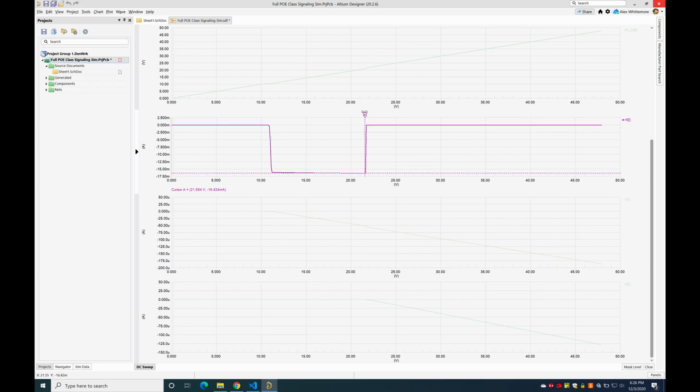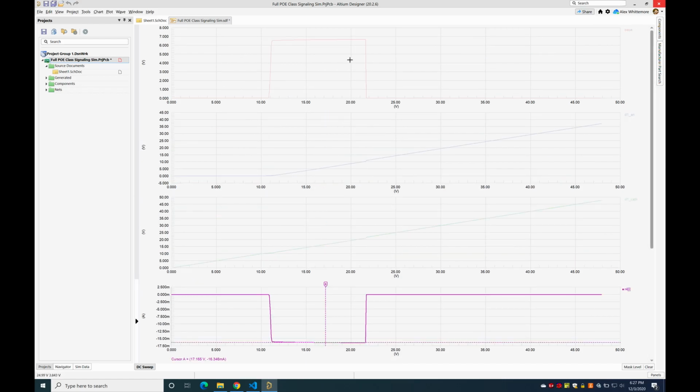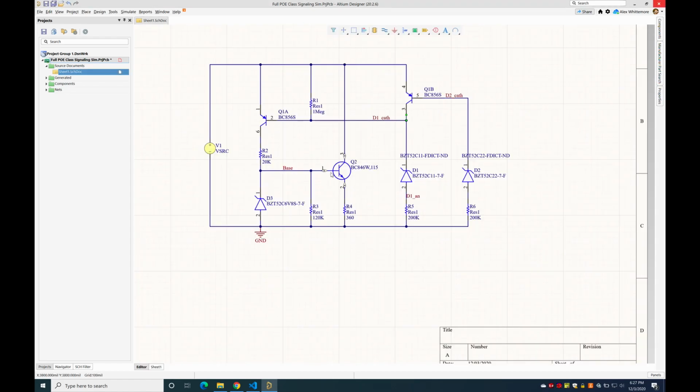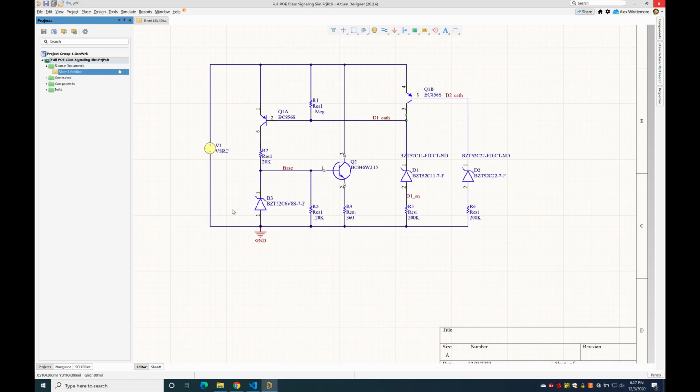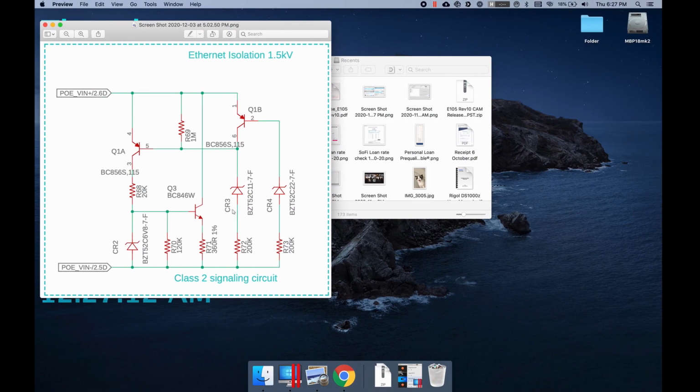So in conclusion, trying to do SPICE simulation with Altium, the things to watch out for are: 1. Port mapping is a little bit fiddly and takes care to make sure that you're doing it right. 2. If you're using managed components, you'll have to redo port mapping on the schematic, at least for now until Altium fixes that. 3. SPICE model errors will fail ungracefully and cause Altium to crash. And 4. Make sure your component values mean what you think they mean in SPICE.